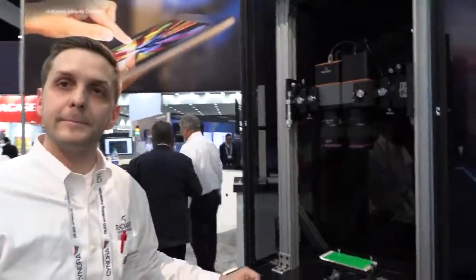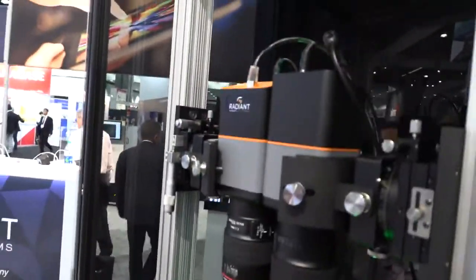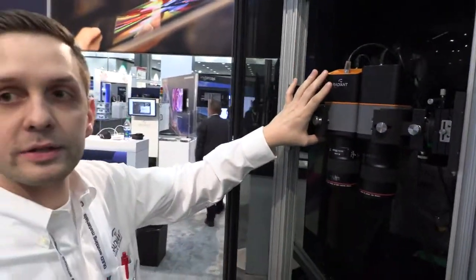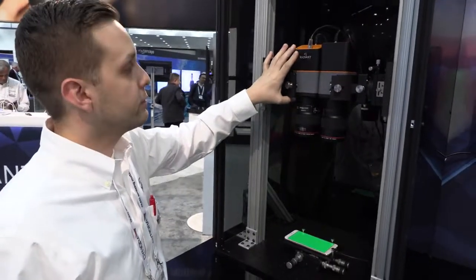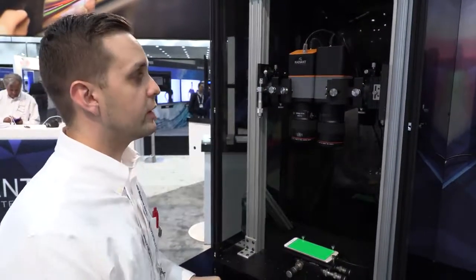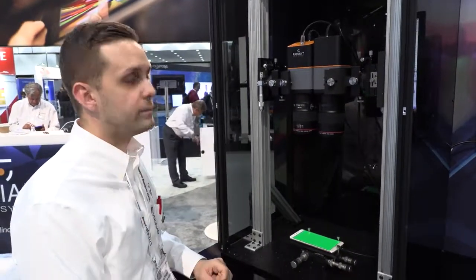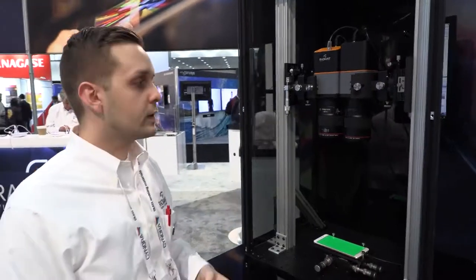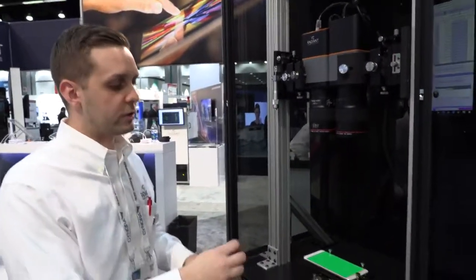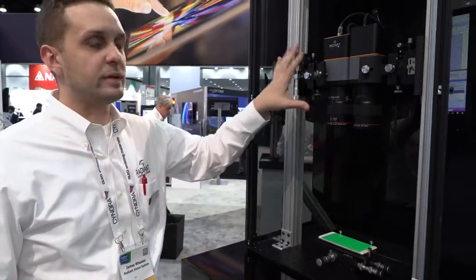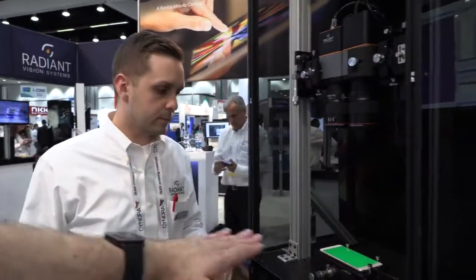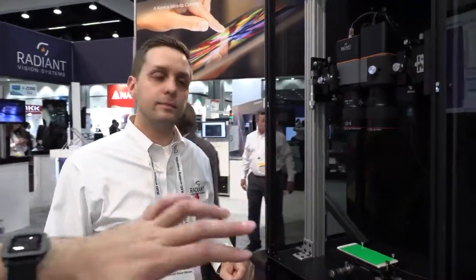And what's special about those machines? They're super high accuracy imaging photometers, so very low noise, a great signal to noise ratio, and high dynamic range. What's a photometer compared to a camera? A photometer means you can only get brightness information out of it. You can't see what color it is. For color you'd want to use an I series, but for this specific application it has to be the Y series. Are you checking if the AMOLED display is in uniform intensity of brightness?